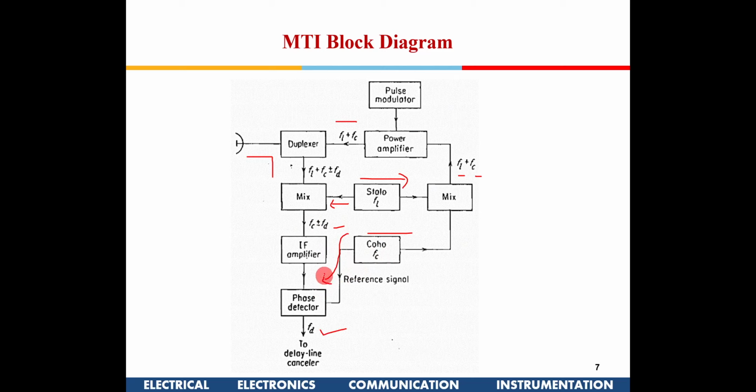Now the advantage of doing it in two stages is this helps me in removing the image frequency, whereas this helps me in having better selectivity. So you could refer to my lecture on communication systems, in which I have explained about superheterodyne receivers and the advantage of having a superheterodyne structure, where you have an IF also, and downscaling the frequency in two steps. In the first step it helps in removing the image frequency, and in the second step you can have better selectivity.